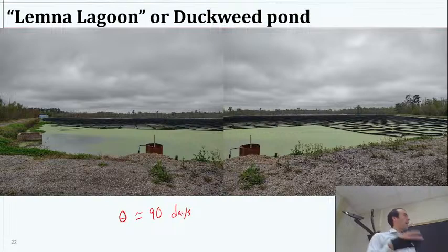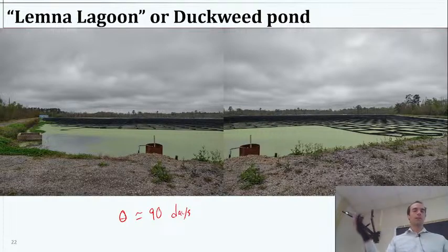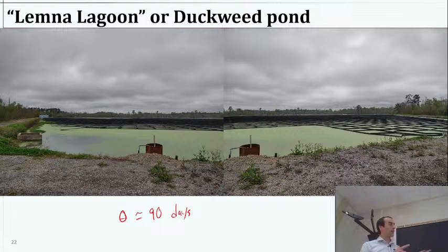The duckweed itself can be harvested instead of the sludge, because it's going to be taking a lot of those nutrients and clumping up. It's actually probably not mandatory. I think you can just let them sit there. Your lagoon itself will accumulate the sludge as they die off and decay. But I think they stopped doing it, but the people who sell this as a product will also provide a harvesting system, so you can take all that duckweed and pile it up and then send it to a landfill or whatever you need to do. But this certainly changes the dynamics of the treatment.